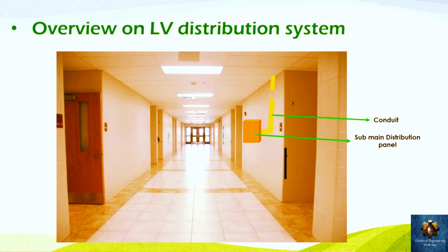And here we go up until reaching this box, which is called the junction box, and we will talk about the junction box later in details. But for now, this junction box is used to distribute the wires, as some wires will go out of it through another conduit, and some wires will go out of it through another conduit. And for the wires which will feed the lighting luminaire, they will go through this conduit, and hence we will have a line and neutral going through this conduit.